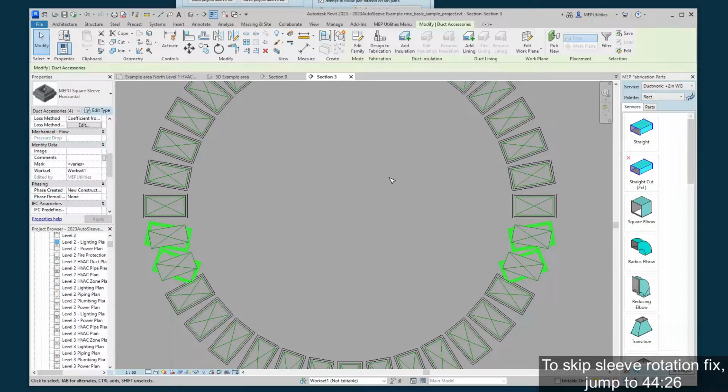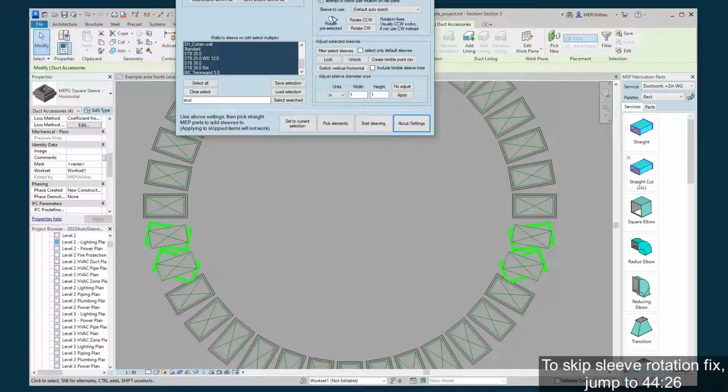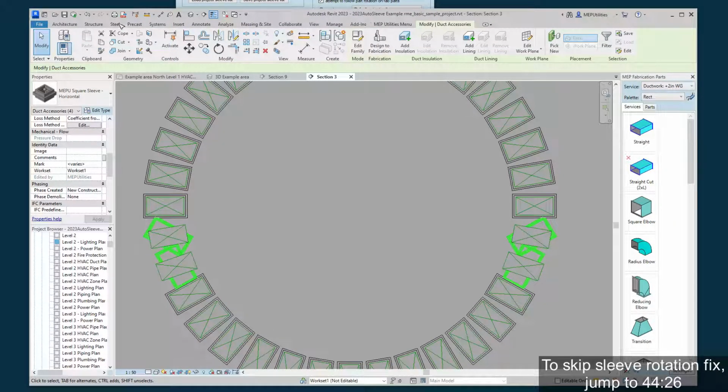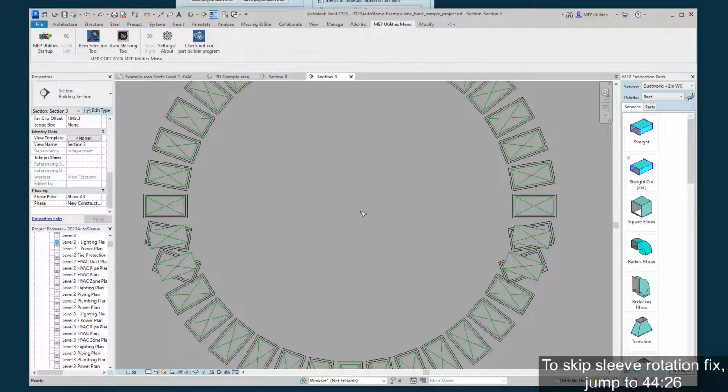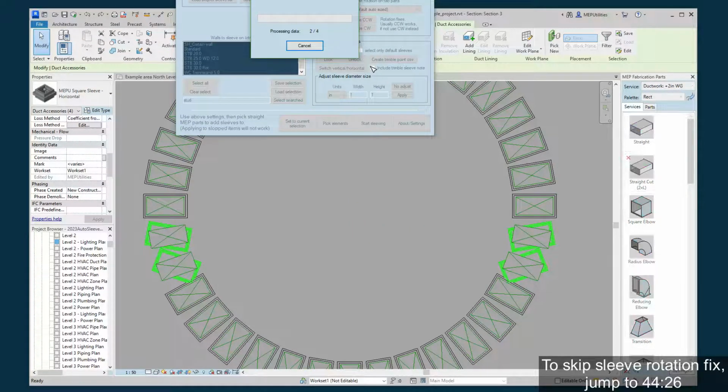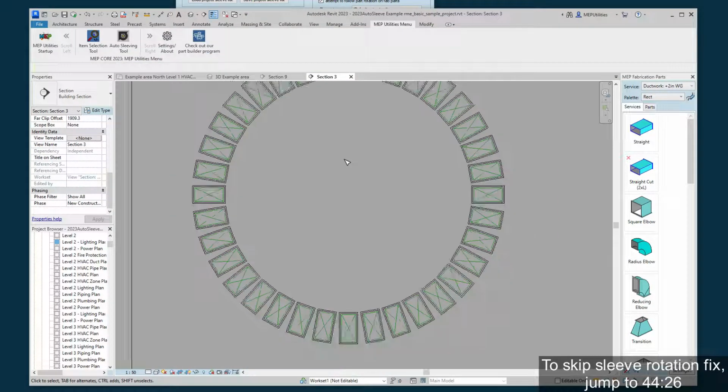And then I finish, and now they're all selected, and now I can do rotate pre-selected, and that'll take whatever you've already got selected and allow you to rotate en masse. So instead of clicking this and getting a selection tool, you'll click this and it'll take what you have and rotate them. So we'll rotate all of those 4 sleeves counterclockwise, which wasn't the direction we want to use. So we'll just rotate them back, select previous, and rotate the other direction, and now they're fixed.